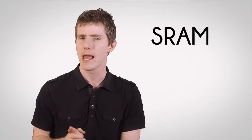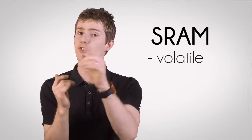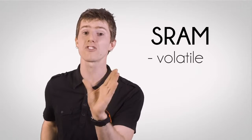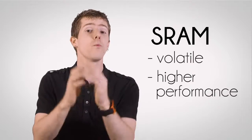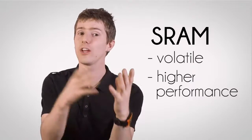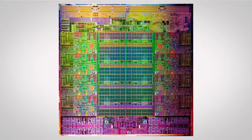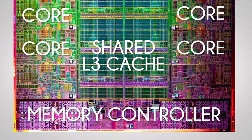Next up is SRAM. This stands for Static Random Access Memory. It's a volatile storage medium, just like DRAM, but the key difference is that it is capable of delivering much higher performance, and that while it's receiving power, it doesn't need to refresh each bit periodically just to keep it from fading. The data will wait instead to be overwritten. Modern high-performance CPUs use SRAM as a way to store the data your CPU needs most right next to it for frequent, fast access. But due to its cost, it's typical for this cache to have a capacity of only a few megabytes.